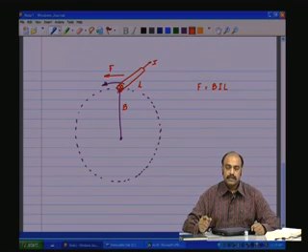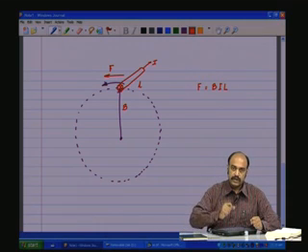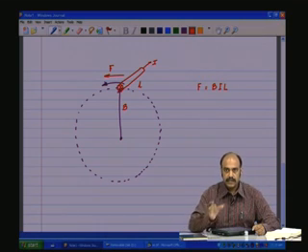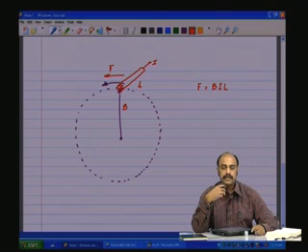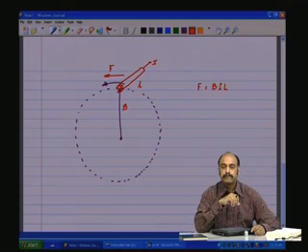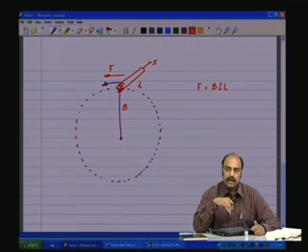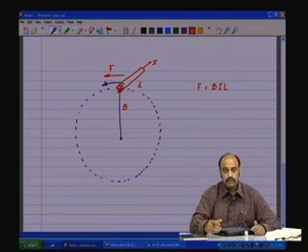And then the rotor starts rotating and tries to catch up with the magnetic field, and the relative speed starts decreasing. As the relative speed decreases, the induced current in the rotor also decreases, thereby reducing the torque to a steady state value.